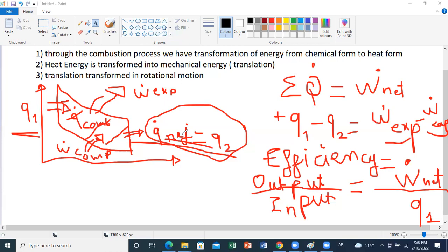So I consider then that this is a way of increasing my efficiency, because it's true that within just my internal combustion engine system, I was not able to profit from it, but I can use it. So my exhaust gases, I can let them pass, for example, through a heat exchanger and exchange heat with the air that is getting inside.